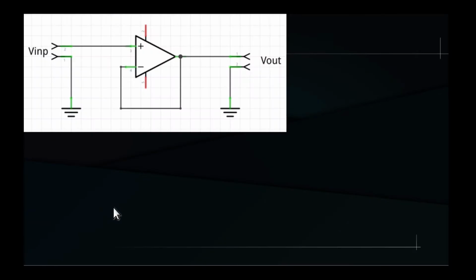The voltage follower is one of the two easiest circuits that can be created around an opamp. In fact, there are no components directly associated with this functionality, just the opamp. To draw the schematic for this circuit, we start once again from the opamp, then we connect directly the output with the inverting input. And that's it! We use the non-inverting input as the input of the voltage follower, and the op-amp output is of course the output of the voltage follower.